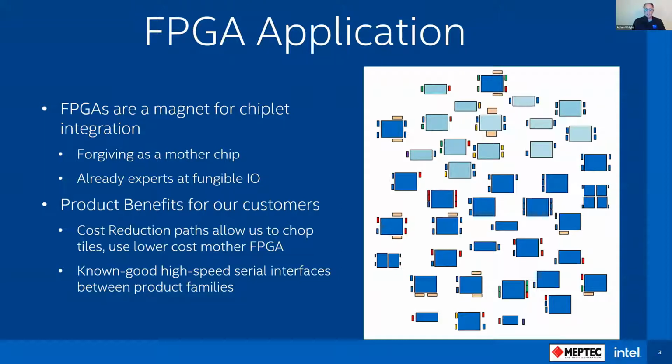The high-speed analog is tricky. If you're doing a new logic chip and a new high-speed analog, you're injecting 2 high-risk designs into the part. So it gives us a lot of make-before-break capability: customers can drop a known good silicon interface into their systems, and then they only have to worry about bringing up the new tile.